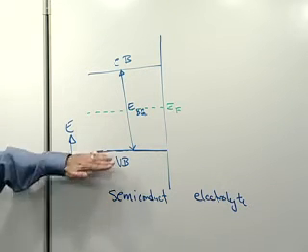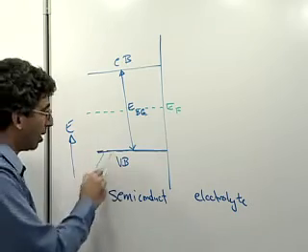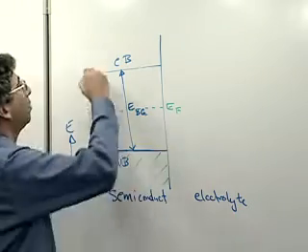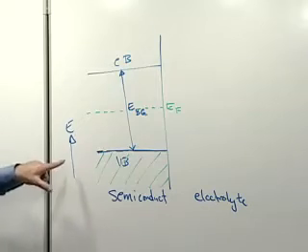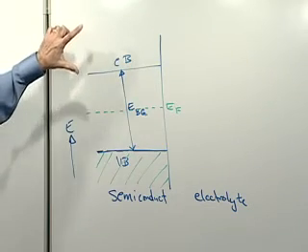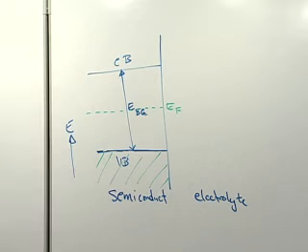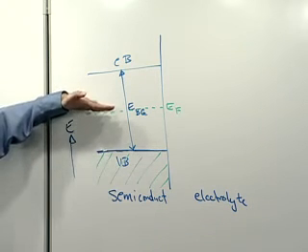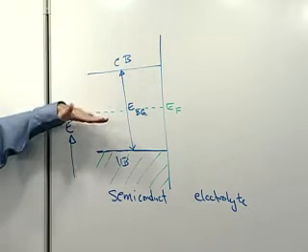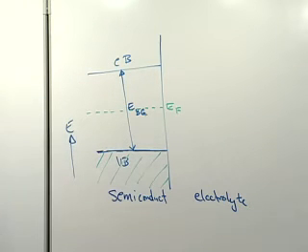Typically in a semiconductor, this bottom set of states would be totally filled. The top ones would be empty, filled with electrons, that is. No electrons up here in your so-called intrinsic semiconductor, your idealized semiconductor interface. And so the average energy of the electrons will be halfway in between the filled and empty states, right in the middle of the band gap.